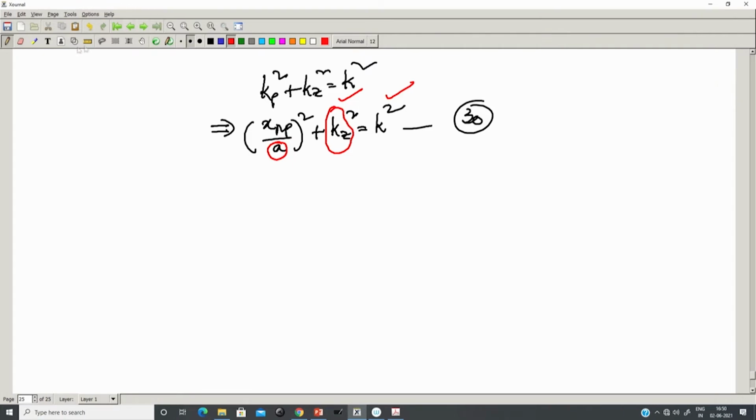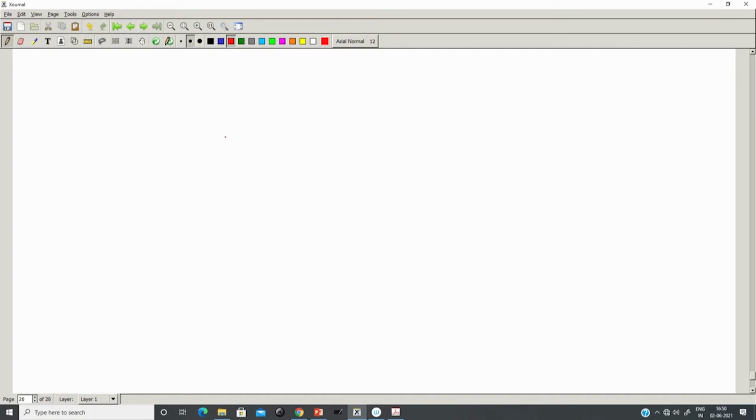Similarly, for the modes TE to Z, they are expressed in terms of the electric vector potential F having only a z component of psi. So, this wave function must be of the form of 25. Okay.